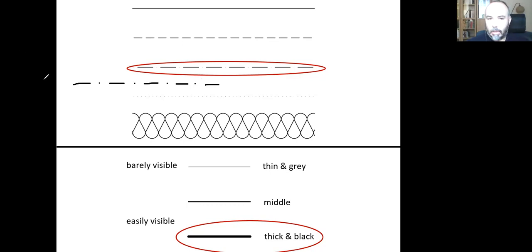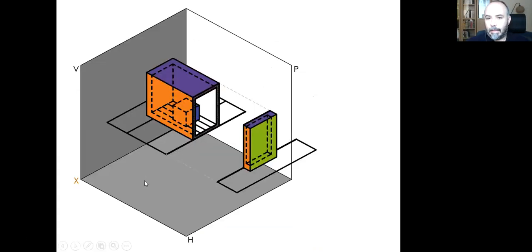Just trust your eye. You need to do a dashed line, a gap, and there should be a point between these dashed lines. So a line, a gap, a point, a gap, a line, a gap, a point, a gap, and it goes like this. And you need to use again the thickest and the most black line weight that you can create with your 2mm pencil. Maybe you can use a 2B or a 3B lead here.